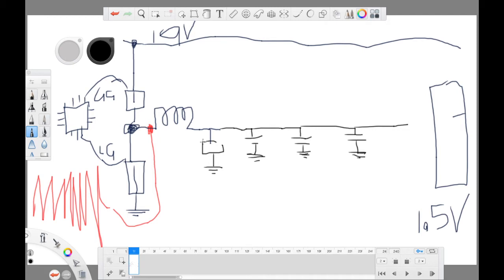After the electrolytic capacitor, now we have a smoother one. Let me just go back and put that again. After the electrolytic capacitor, when you check with your oscilloscope, you'll be shocked that you have a more smooth output.